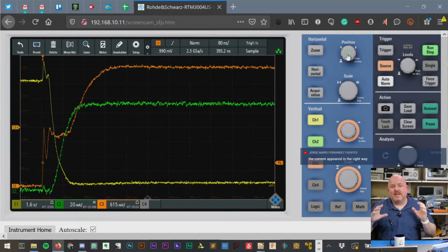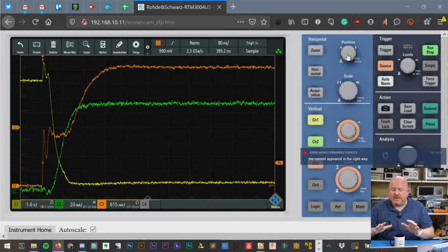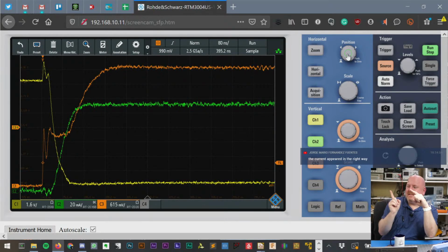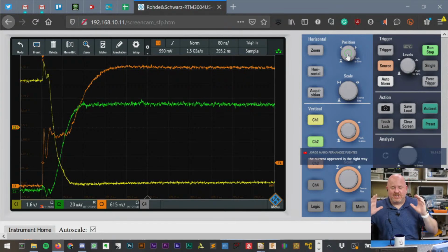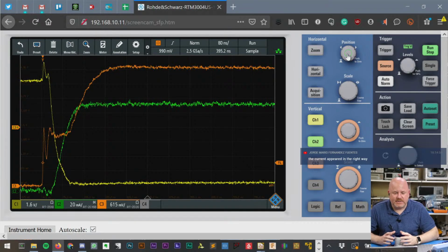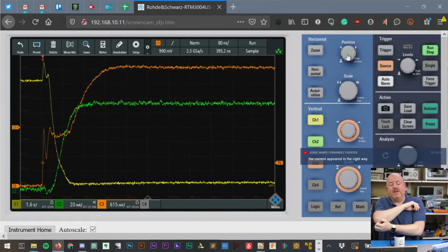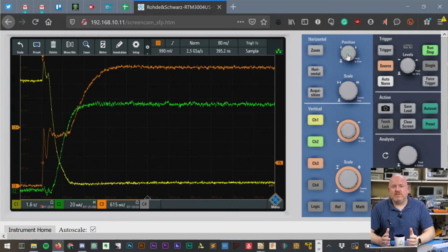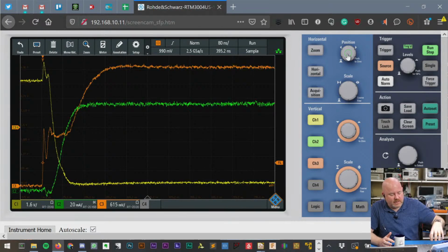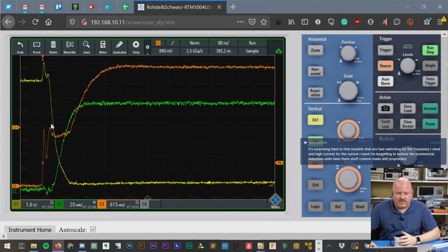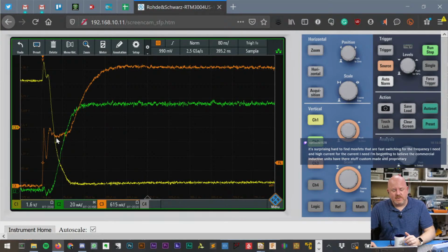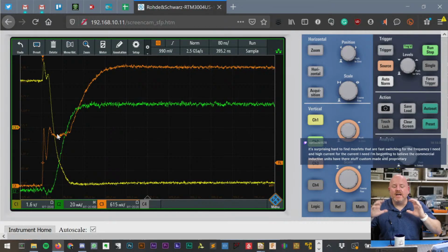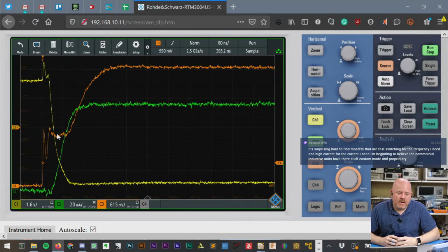By the way, because I'm a total nerd, when I got this to show up on my scope, I was super excited because this is something I had wanted to measure for a very long time, and I was finally able to. Now, you might be saying, but James, there's no current limiting resistor, it's fine. The MOSFET turns on. If you've ever read anything about MOSFETs, you might have read about the Miller Plateau. We see it, it's supposed to be doing that. Why is there anything wrong with this circuit?